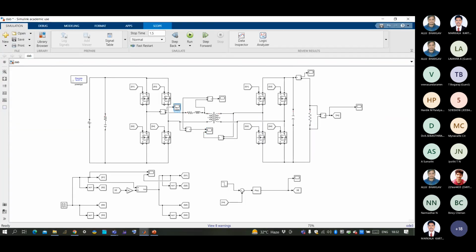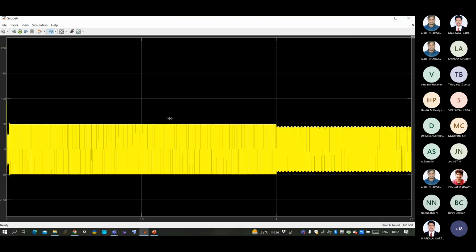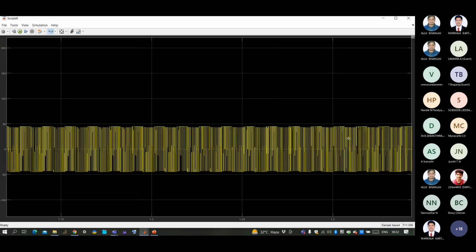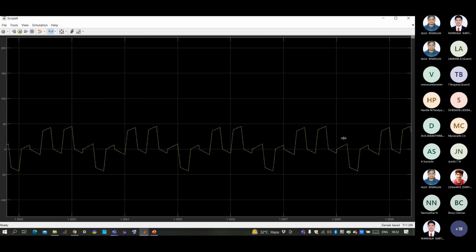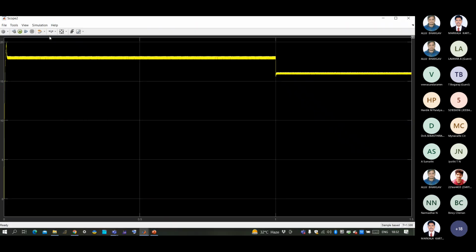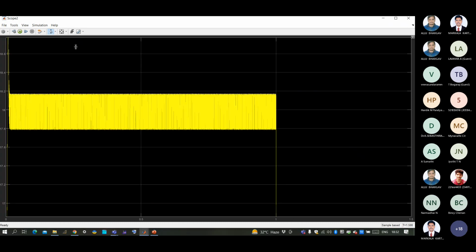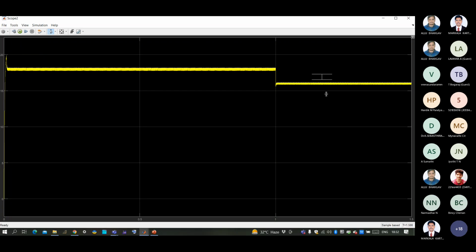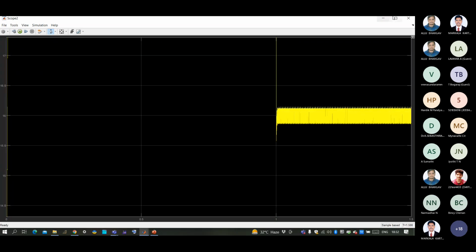And this will be the inductor current value, and you can check it out. This is the inductor value, and you can see the output current. I didn't show the initial output current. Initially it was 360 by 20, giving some 18 amperes. And now it is changed to 320, so it gives 16 amperes, and it will maintain 16 amperes.